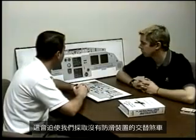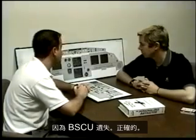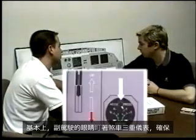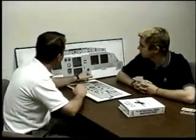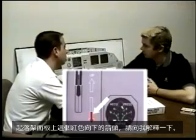It's going to force us into alternate brakes without anti-skid because of loss of the BSCUs. Right. What is your anti-skid detection now? It's basically your first officer's eyes on the brake triple gauge, making sure that he doesn't have in excess of 1,000 psi.